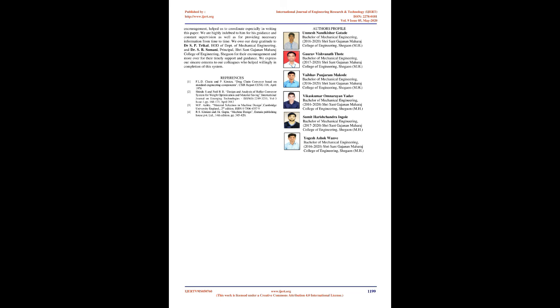V. Conclusion. In this paper we addressed the optimization problem of the drag chain conveyor system, which arises due to overweight of the support chassis, less coal outlet capacity, and vibrations in the bottom chassis. The objective of this work was to modify the present design of the drag chain conveyor system with the CAD application SOLIDWORKS 2018. The proposed design allows optimization of the drag chain conveyor system, which results in an increase in coal outlet capacity, reduction in weight of the support chassis, increase in fatigue cycles of the shaft, and reduction in vibrations in the bottom chassis by proper material selection, analysis, and design calculations of the drag chain conveyor.